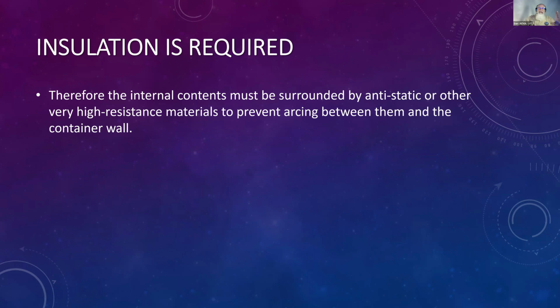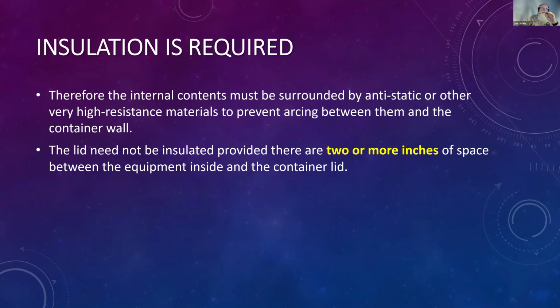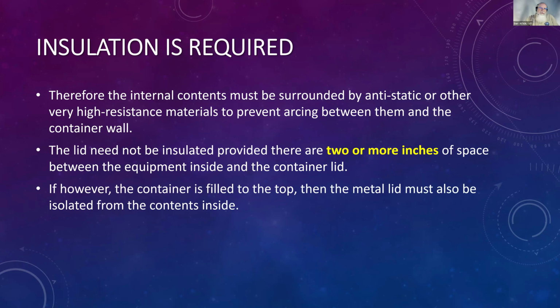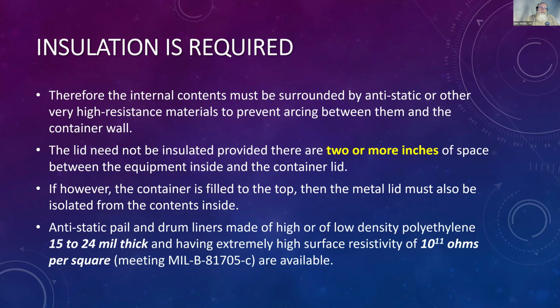So you not only need to have the appropriate container, but you also have to have an anti-static bag and space or distance between your devices and the surrounding container, whatever that is. The lid does not need to be insulated, provided you have at least 2 inches of space between the equipment. If it's, however, filled to the top, then you also need to isolate the lid from the contents.